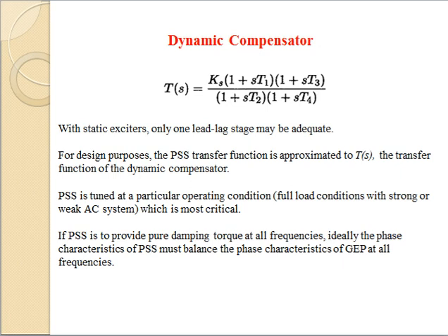So what is happening in the operation of the overall power system? There are three main systems. One is your rotor, another is flux decay, and the third one is your excitation system. Whenever signals are passing from one sensor to this power system stabilizer through the excitation system, and you are going to damp oscillations, there will be some lag because of these signal transfers, and you are ultimately going to compensate that lag with the help of this lead compensator.